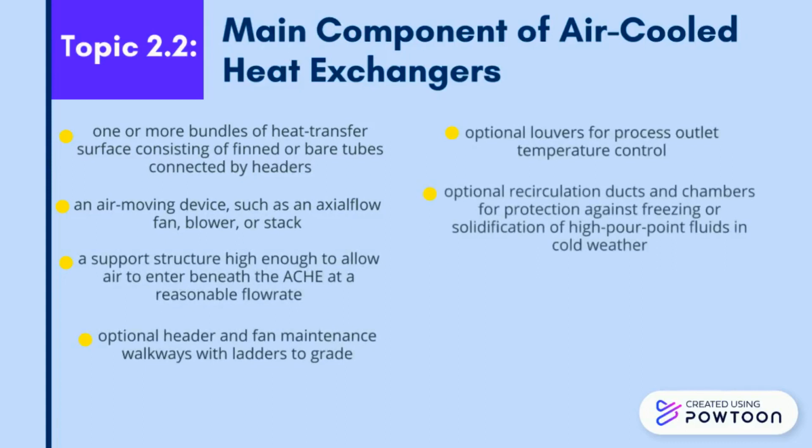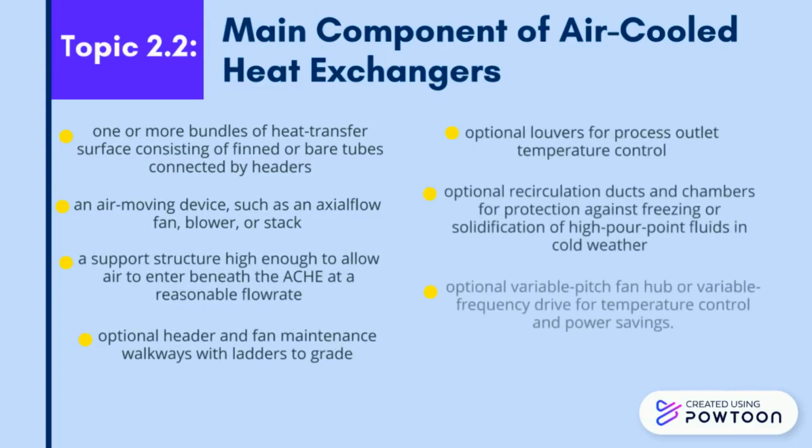5. Optional louvers for process outlet temperature control. 6. Optional recirculation duct and chambers for protection against freezing or solidification of high pour point fluid in cold weather. Last one, optional variable pitch fan hub or variable frequency drive for temperature control and power saving.